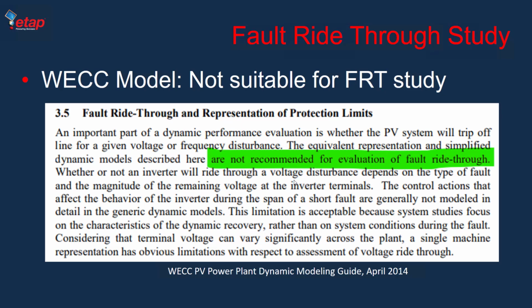So when it comes to fault ride-through capabilities, the WECC documents or even the IEC documents claim that these models are not recommended for evaluation of fault ride-through. The WECC models are developed for system planning studies, where you're trying to study your system and your wind farm or solar farm or generation plants are typically far from a disturbance, and you're not looking at events or severe disturbances happening close to them, and you're trying to use a generic model when you're studying your systems, and you're not very impacted by one individual WTG in the system.